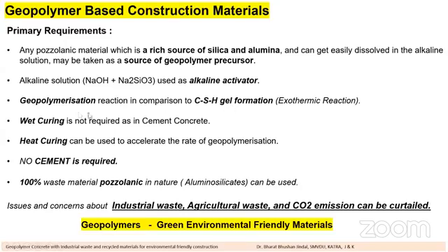So that means if you use geopolymer based material, wet curing is not required as it is required in cement based concrete. So no curing is required at all. But you can do heat curing or steam curing to accelerate this process of geopolymerization, because the rate of geopolymerization will influence the setting properties of the geopolymer based material, geopolymer concrete or geopolymer mortar. So the interesting part is no cement is required.